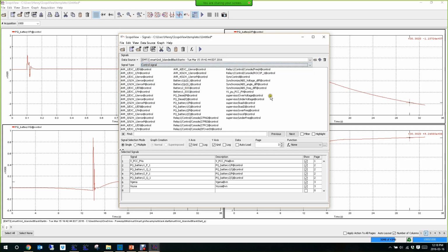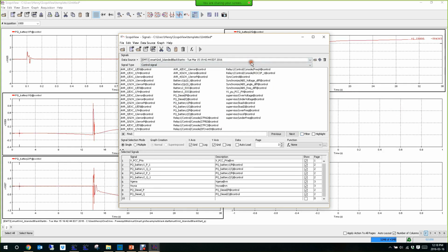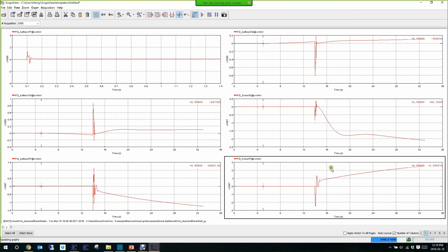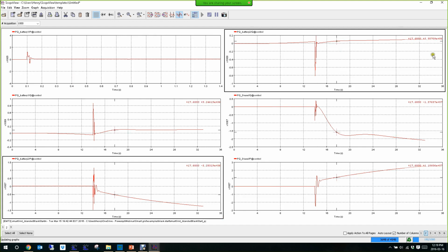Now it's here. Power diesel, and it's on page 2. Okay, so you see the diesel. There are those two here. We start ramping the power here, like we said. Because we produce power and the loads are not connected yet, the batteries are taking this power. So you see the battery here that is taking the power. Another thing we can see is that I probably didn't enable the droop control in that case. That's why both batteries, which are here and here, don't accumulate the same power.